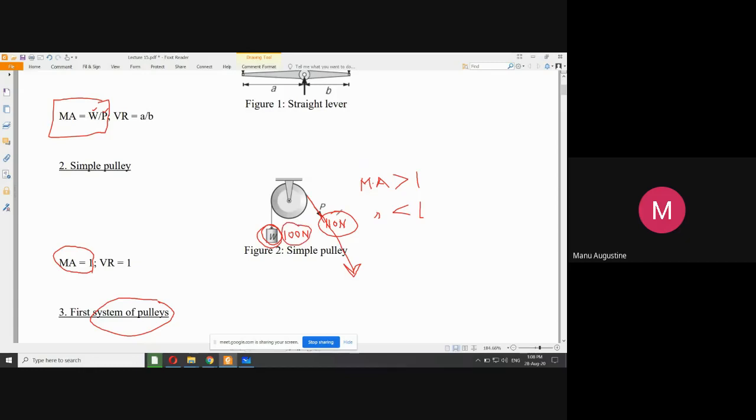And how does that happen in the first place? It is because the hinges of the pulley, the rotary or rubbing parts that allow the rotation of the pulley itself, have developed some rust or corrosion, due to which it has a lot of friction. So due to the presence of frictional forces in the moving parts of the pulley, the effort that you have to apply is larger than the weight you are lifting.